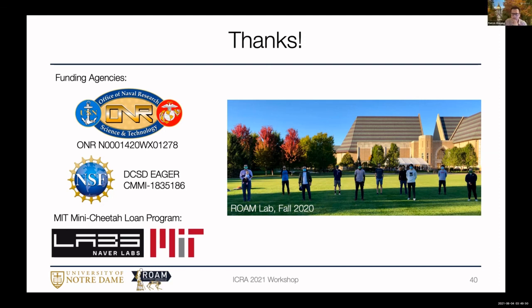Yeah, I think that's a great point. So here, the policies that we've been looking at are linear state feedback policies that are in joint space. There was some really nice work out of Ludovic Righetti's group presented by Bilal Hamoud earlier this week, where they were looking at optimizing impedances for uncertain terrain interactions.